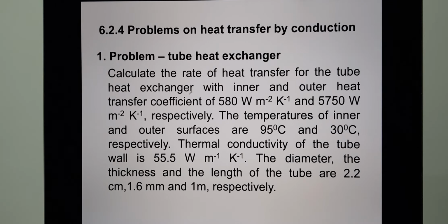So what you need to do for this particular problem statement? It has been stated in the first statement: calculate the rate of heat transfer, meaning you need to calculate the value of Q. Then when you read along, it is tube heat exchanger with inner and outer heat transfer coefficient, meaning that this one is heat transfer in series.